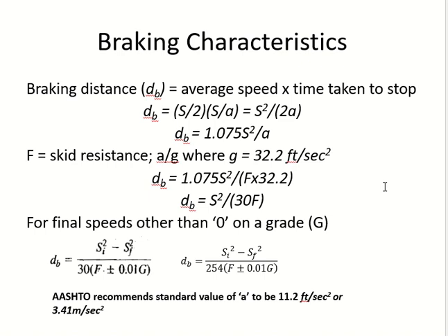One thing is the final speed. And the second thing is the gradient. Does the gradient have an effect on the braking or not? Yes, it does, right? So it should be part of the equation. So this is the final equation after incorporating the gradient and the final speed: initial speed, final speed, and the effect of the gradient. It takes the speed in miles per hour and gives you the distance in feet; the speed in kilometers per hour, distance in meters. The conversion factors are already there.